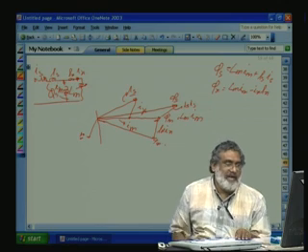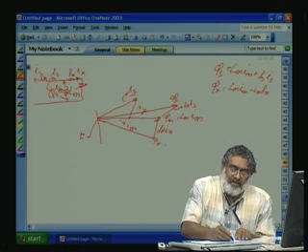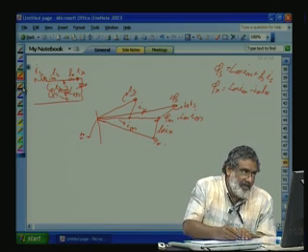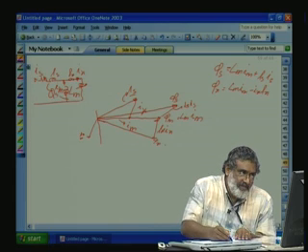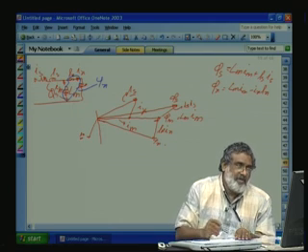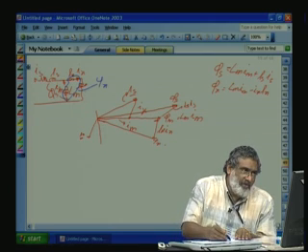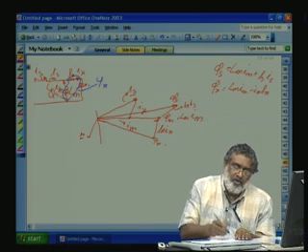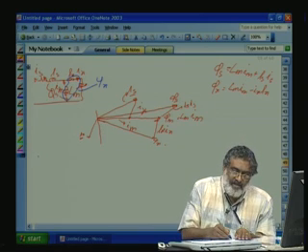If you see from the equivalent circuit, psi r is the flux which couples the rotor, that is, the flux coupling this inductance. After psi r, you only see the resistance, so the voltage across the resistance RR by S.